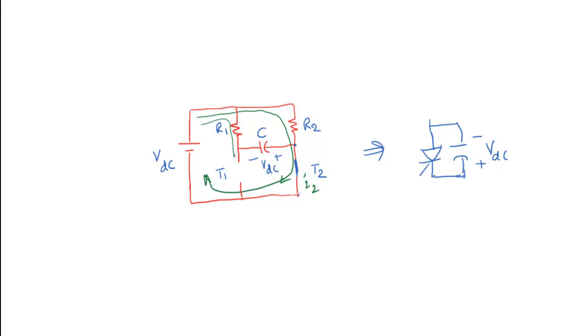Now the capacitor will be discharged through the main thyristor T2, but this current will be there only for some time. How exactly? Once this capacitor is discharged, the voltage polarity will disappear. Then it will be charged again by the source voltage in the same direction.